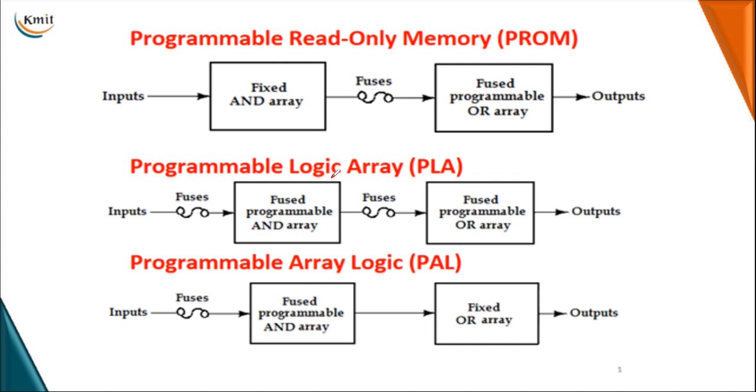Whereas in the programmable logic array, you transfer the inputs through the fuses to the AND gates or AND array, and you don't have minterms. Based on the required product terms, you can program your AND gates, and we can obtain the specific AND functionality from this programmable AND array.